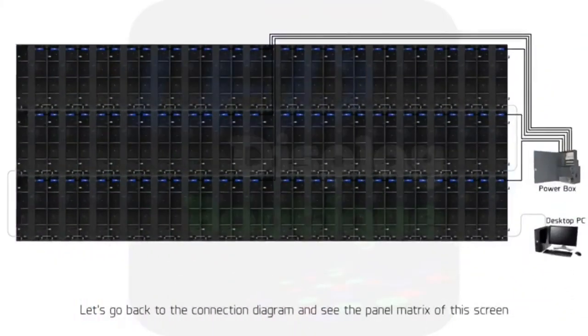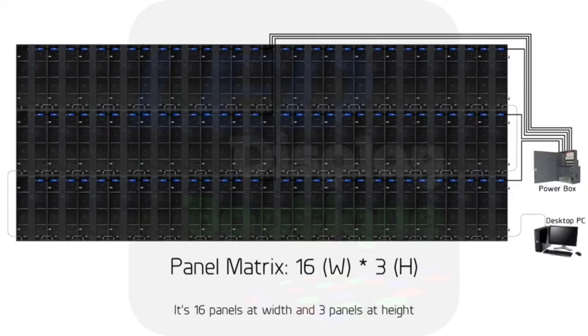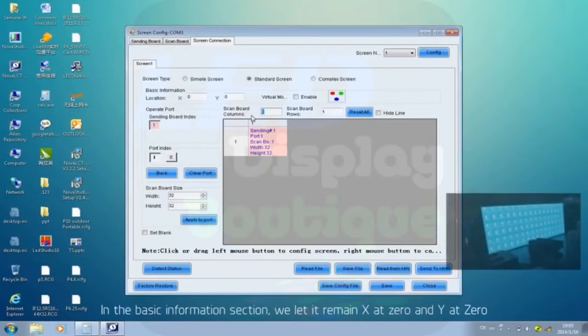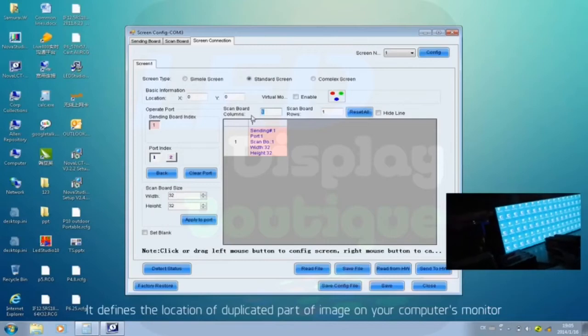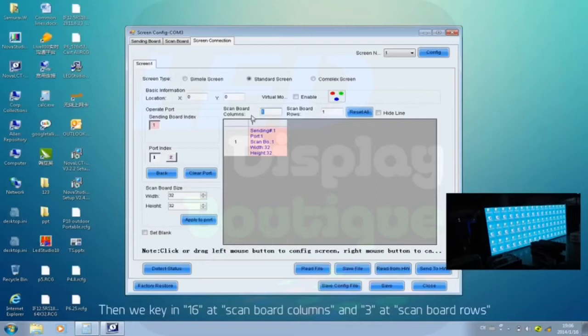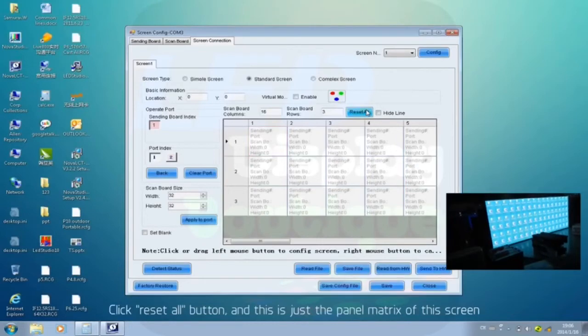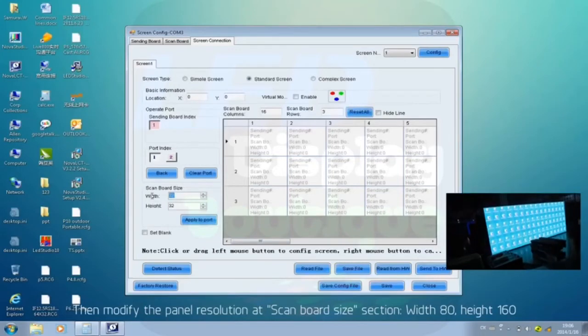Let's go back to the connection diagram to see the panel matrix of this screen. It's 16 panels at width and 3 panels at height. In the basic information section, we'll let it remain X at 0 and Y at 0. It defines the location of the duplicated part of the image on your computer's monitor. Then we key in 16 as scan board columns and 3 as scan board rows. Click the Reset All button, and this is just a panel matrix for this screen. Then modify the panel resolution and scan board size section, width 80, height 160.